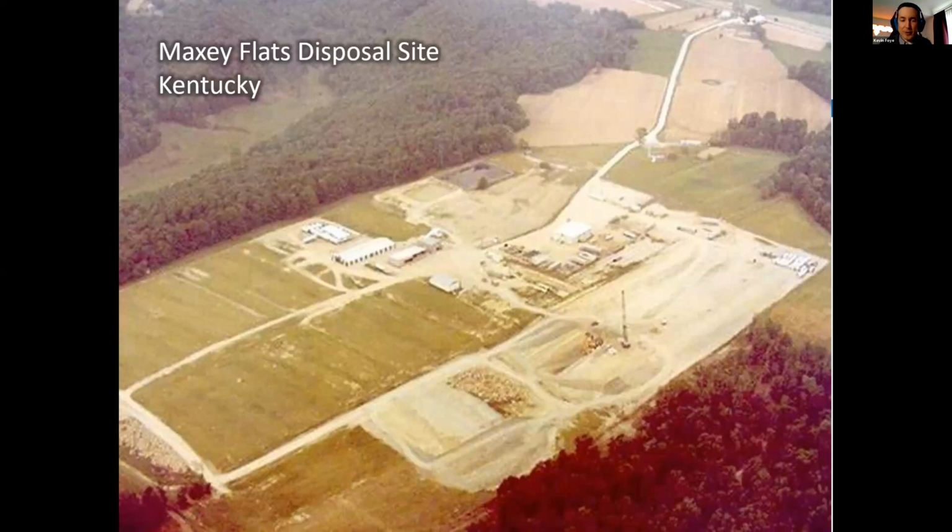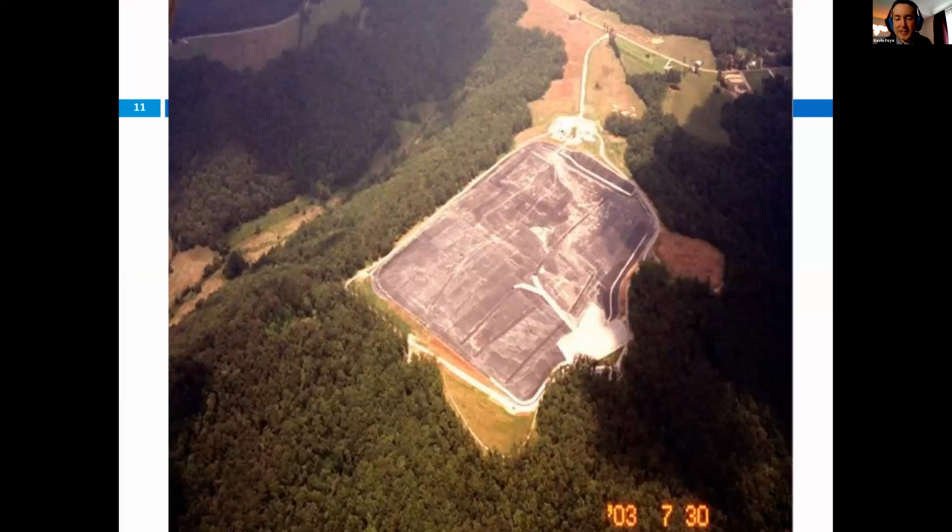After that, this is a picture that was taken in the early 2000s. They had constructed first in the early 80s, and then again replaced it in the 90s, a temporary cover, which was an exposed geomembrane. That's what's giving the black color that you see here. And that shed stormwater much more effectively than a soil cover, but it was considered an interim solution. And I'll go into a little more detail on why it was considered an interim solution. But the idea was to very quickly get to a point where new stormwater percolation to the site was controlled.